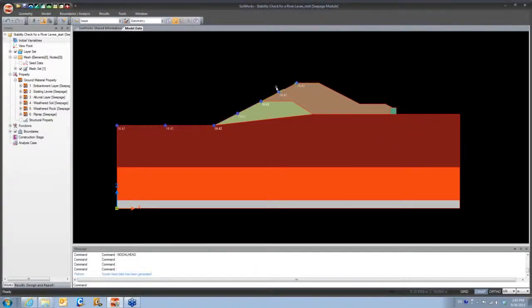So now all of my curves here to the left have 18.42 assigned to them, because that's where my static water level is. Do you see the boundary assigned to the left side?